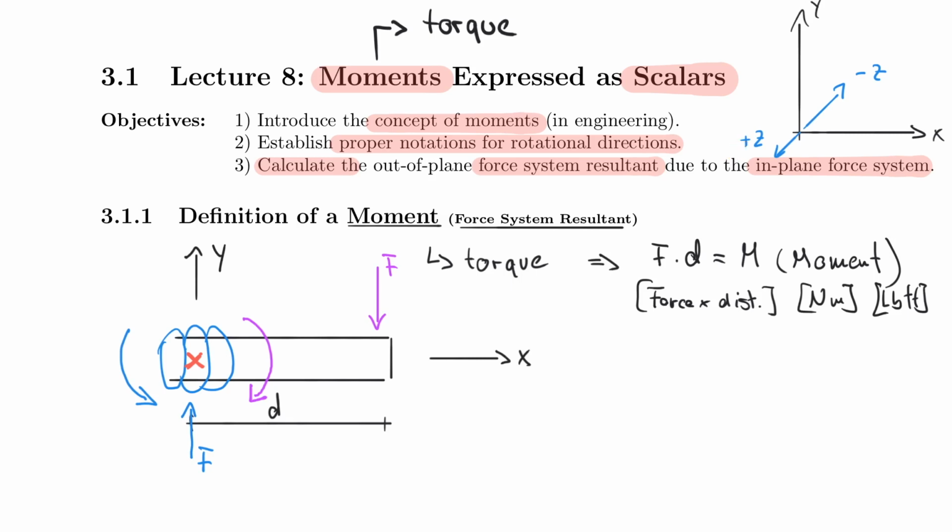And vice versa, if you rotate from, let's say, positive y to positive x, you actually end up with the negative z direction. And that is why we can describe this acting moment here, which is the force times the distance, and the reaction moment also by clockwise or counterclockwise, where clockwise actually would be a negative rotation, right? So clockwise is a negative rotation if you think about this.